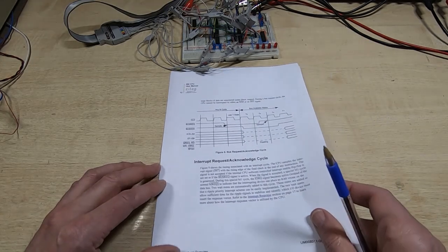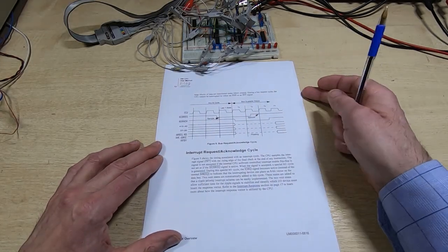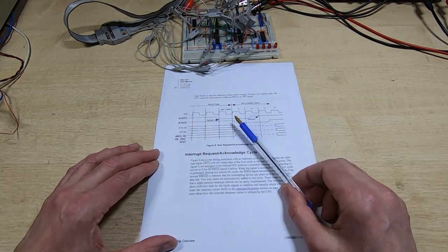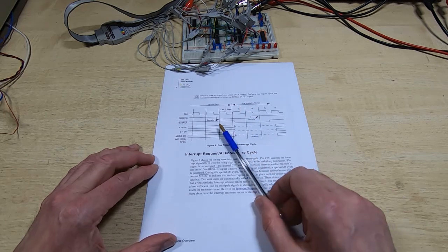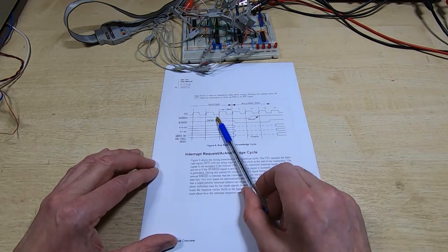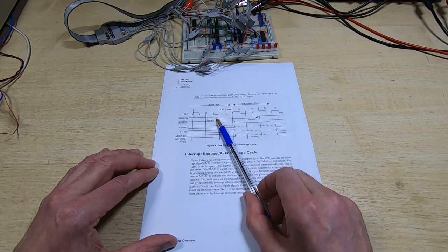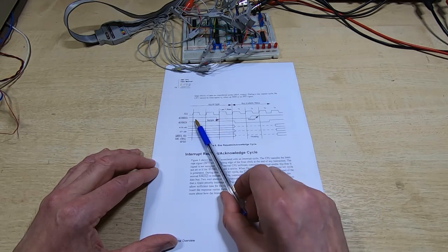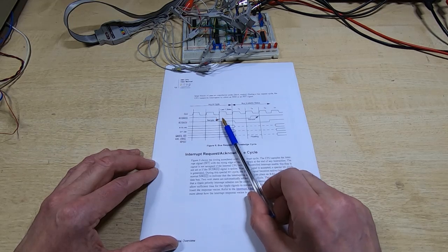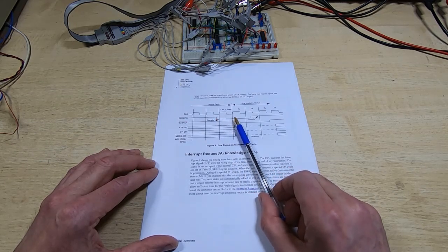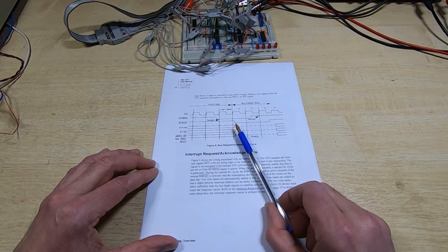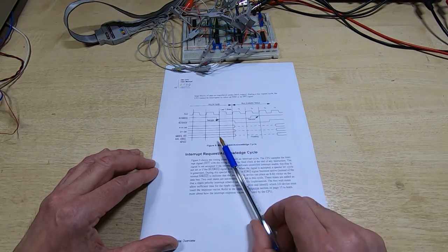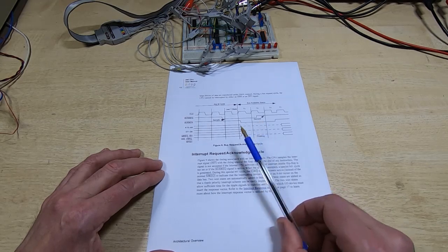So we'll look at the relevant page from the Z80 handbook that shows us how to get control of the address bus, the data bus and various control lines. All we have to do is pull the bus request line going into the Z80 low, and we can do that at any point in any M cycle, and at the end of the current M cycle the Z80 in theory should put the address bus into tri-state mode, it should put the data bus into tri-state mode, and it should put the various control lines into tri-state mode, so they're all floating.